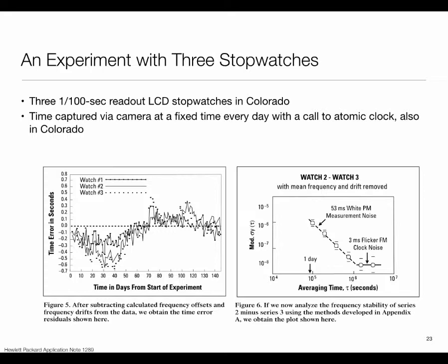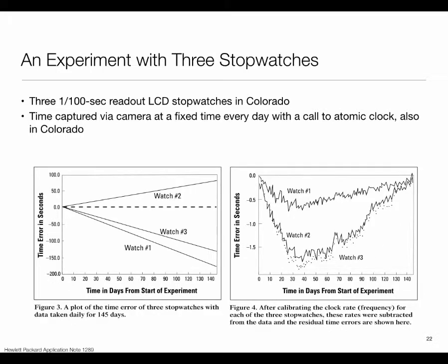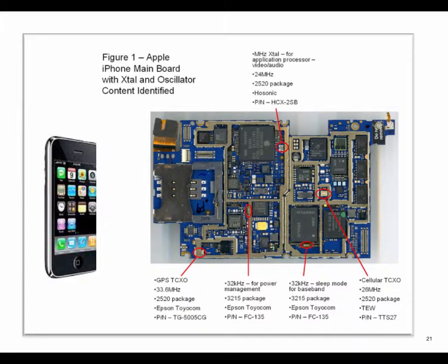So at the end of the day, what we have are non-ideal clocks, and somehow we need to compensate for these things, because were we not to do that with the kind of oscillators we can affordably use, standard crystal oscillators, we'll see our computers diverging very, very rapidly, and it will not be good. We did see these things called TCXOs. These are temperature compensated. They can get you down to 1 ppm type accuracy, whereas standard stuff would be 40, 50 ppm, so 40, 50 times more unstable.